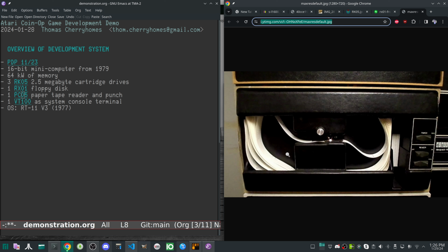stack of paper tape, which is literally paper that has whole bunches of little holes punched in it, one line for each binary byte with 8 little holes plus a sprocket hole right in the middle of it to keep everything in line. It has a little optical reader in the middle that's basically looking at the holes and turning those into binary digits and bytes to go right down the line to the controller. In addition to the reader, the right-hand side that you can't see very well is actually the punch. So this is how we create the tapes.